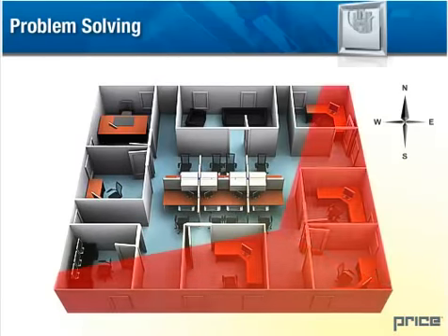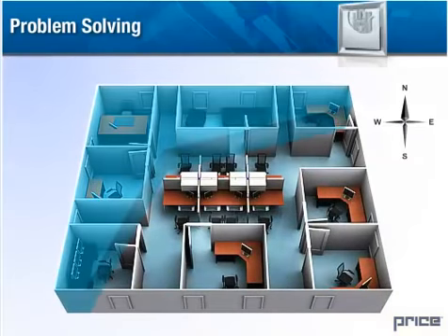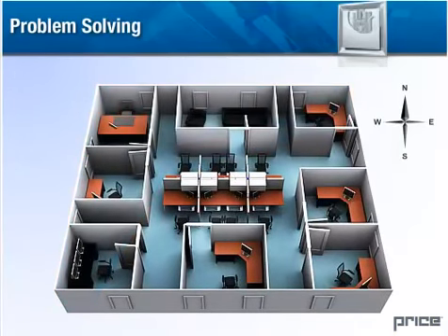The south and east side of the building experience a greater solar load than any other portions of the building, and will require a larger cooling period. The north and west walls will require a larger heating period as the solar load for these faces is smaller.